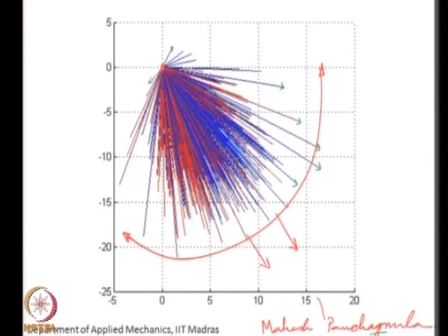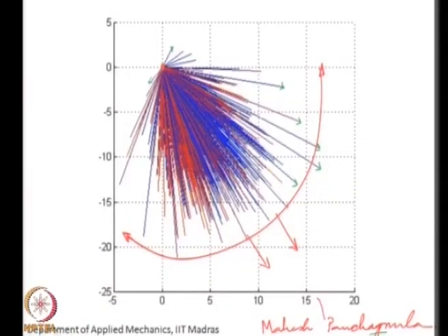and this variation in the angle of the direction chosen by the drops is represented as size velocity correlation, because what we had there is like an axial velocity. So, even if they were moving with similar axial velocities or similar magnitude, similar speeds, because they were moving in slightly different directions, you tend to get a different axial velocity. So, this plot here shows you what we call our mean velocity of the droplet phase. We talked about droplet phase in the context of multi-phase flows. The mean velocity in the context of a droplet phase is this one arrow.